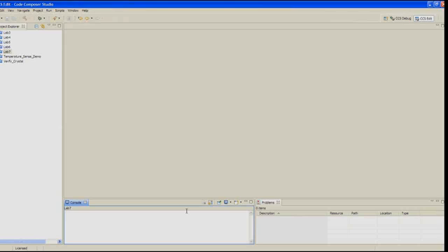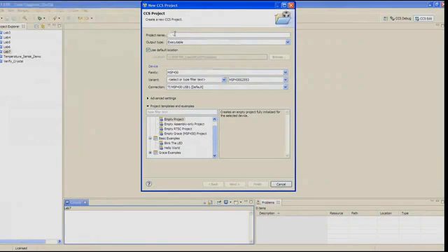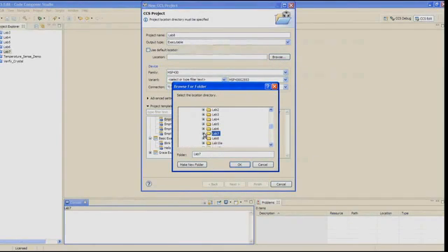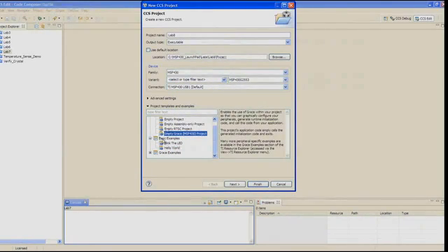Grace is part of the CodeComposer Studio 5.1 installation. Create a new project by clicking File, New, CCS Project. Go ahead and make the selections shown in the workbook. Again, if you're using the 2231, make the appropriate choices for that part. Make sure this time that you select Empty Grace MSP430 project before you click Finish.